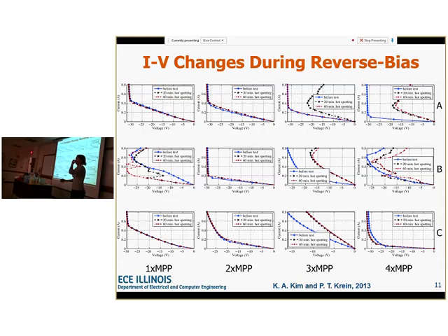But actually, as Professor Palawa mentioned, it's hard to quantify in which conditions we're actually going to have the reverse biasing happening. So in certain conditions, even in a 24 cell string, which is relatively short in the standard, you can still get one cell reverse biased pretty far past 2 times the maximum power point. So the short answer would be to decrease the string length, make them maybe 3 or 4 cells, and then you'd be pretty good. If you really want to be safe, you'd do every single one, but studies have shown that's actually not worth it. It ends up being more work than it's worth.